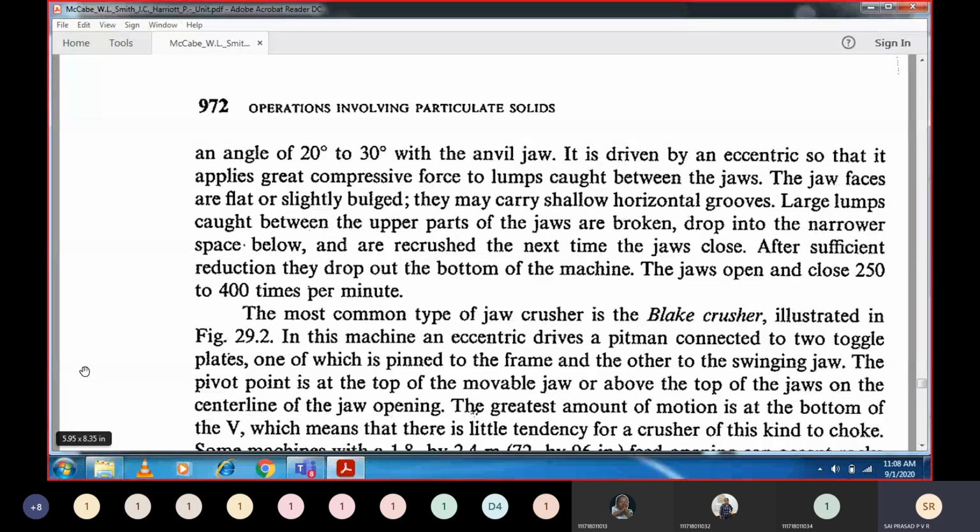As you know, the jaws are made of hardened materials, especially stone, but they are not smooth; they have some stampings on them. Rectangular stampings are there. These are called the grooves, which increase friction, and because of this we can easily nip the particle. Once we nip the particle firmly, we can apply force on it, and the particle breaks because of compression only. Remember, a Blake type of jaw crusher uses compressive force only to break the size of the particles.